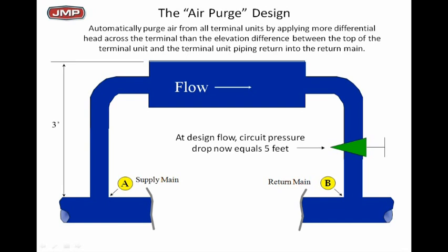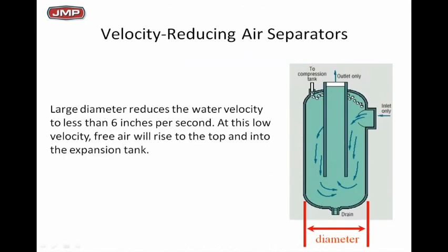Nice little trick for some of you senior engineers listening to this. You may have never heard of this. It works like a charm. You just got to spend a little bit of time sizing your pipe properly, and you may have to actually put a circuit setter in there and put a little extra pressure drop to make sure you get the water up that high. Cute little idea, and I really think it makes some sense.